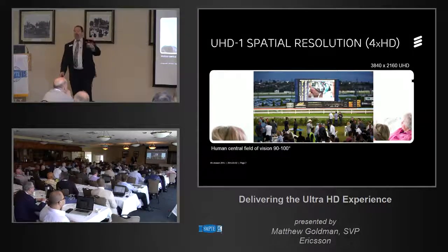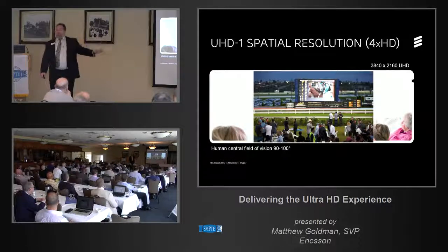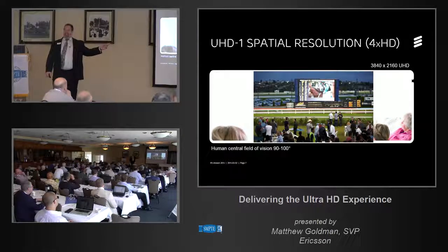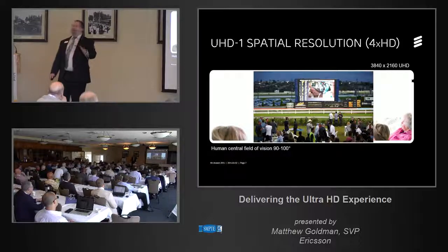Now, what if you're not at the proper viewing distance? As I said, if you're too far back, UHD will look like HD or SD, because that's what it looks like to you back there, okay? If you sit too close, what's the problem? You see the pixel structure of the television, so there really is that sweet spot. It's not exactly at 3 heights or 1.5 picture heights. It's somewhere around there. It's a little bit fuzzy.